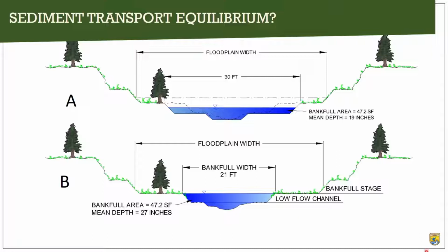So the flows up to bankfull stage have been shown to be responsible for forming and maintaining the channel features and transporting the majority of sediment in alluvial systems. So this relationship between depth and shear stress helps us understand why that we just talked about.